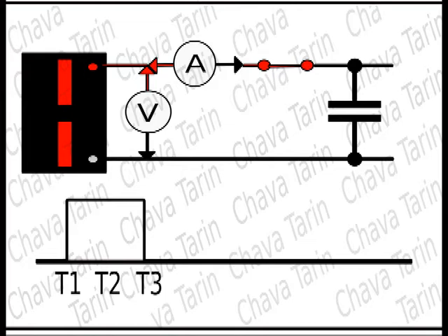Therefore, when turning on the switch at time t1, the current is so intense that the voltage is sort of short-circuited and it drops to zero. A fraction of a second later, at time t3, the capacitive load no longer allows more current to flow. We see that the current is leading the voltage. This is called current lead.